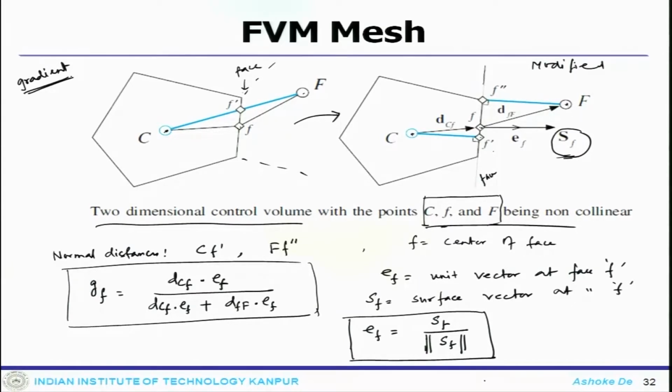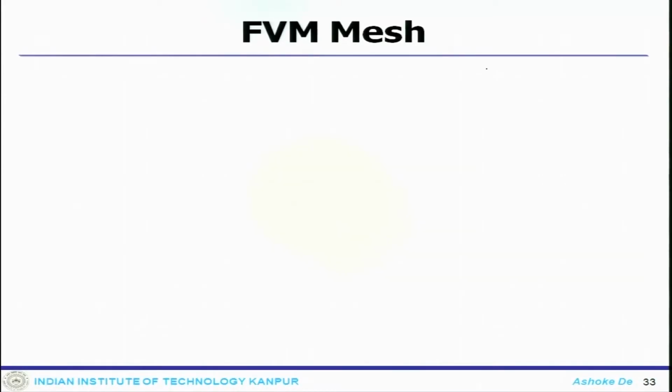which is the calculation of the gradient, which involves some derivatives. So, once you have some derivative calculation, then you need to calculate things at the flux, because the gradient calculation is always defined at the face. So, when you come down to the face, then flux calculation is a must, and there you need to have this normal calculation and all this.